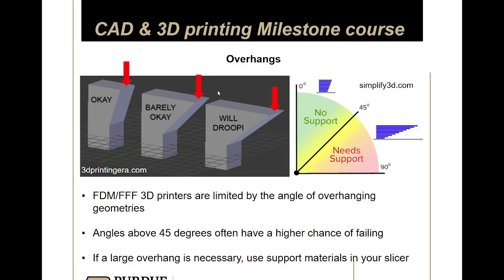Generally, the rule of thumb is that you make everything at a 45-degree overhang at a maximum on the z-axis. Obviously, if your geometry needs to be more than that, then it's going to have to do that. But in general, 45 degrees is the gold standard. It's nice because it's in the middle between 90 and 0. So adding a chamfer is a 45-degree overhang.